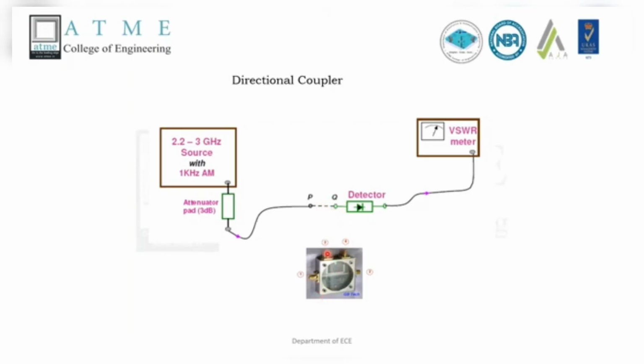And now we have to switch the terminations, that is port 2 and port 3 have to be terminated with a 50 ohm matched load.